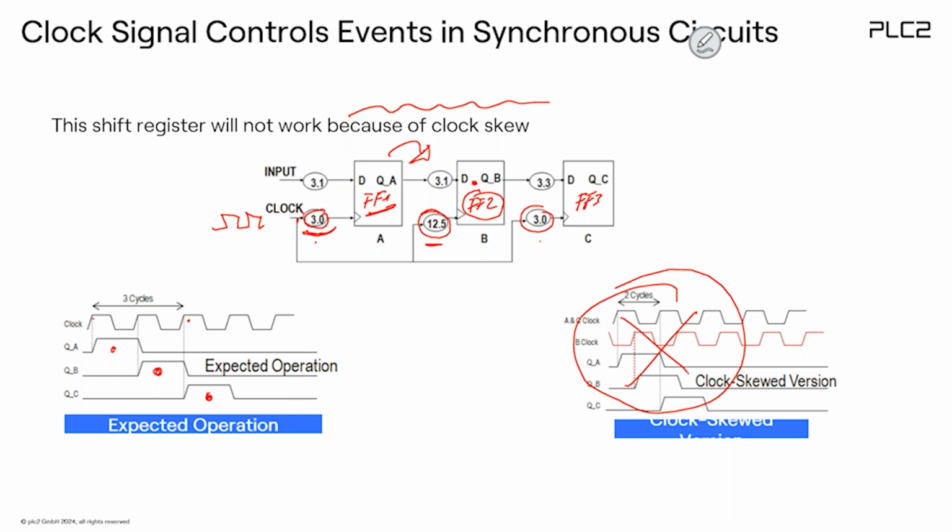And then just imagine, again, it depends on the environmental condition. If you have a best case, the skew values might be small, so the shift register might work. But if you have a worst case condition, long delays, then your circuit will fail, and you don't really know what happened. My circuit failed. What happened? So that's the problem. We have to maintain a proper clock signal.